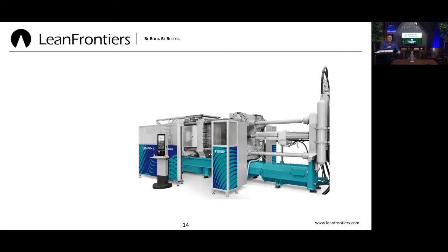But of course, we had to batch with them. We had to build up all the castings. We had to sort them and keep them before they go into machining. Well, in the cause of one-piece flow, ideally, I would like to see the die-cast process right into the machining line. But just due to the size of the machine, the complexity of the machine, the cost of the machine, we obviously couldn't buy a die-cast machine for each machining line when we were machining aluminum in this case.